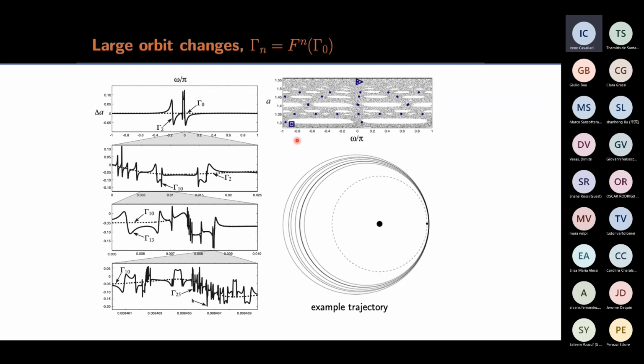And if you look at the trajectory in the inertial space, this is what you get. We started out at a large orbit, but after several passes, we're decreasing the semi-major axis. Actually, we're decreasing the apoapse and keeping the periapse the same.